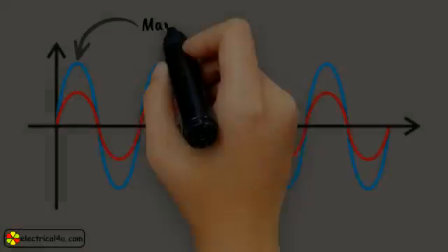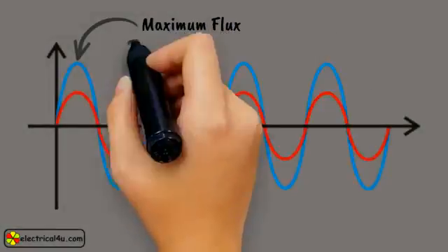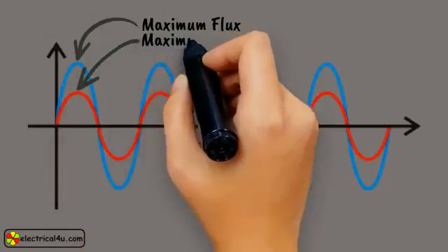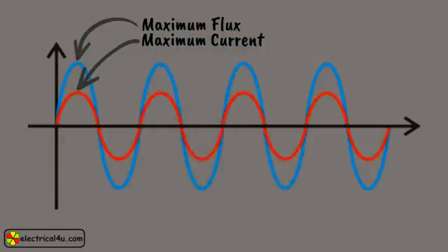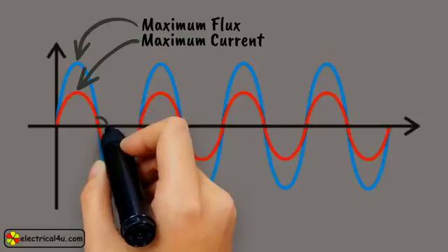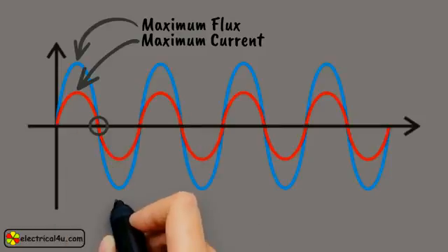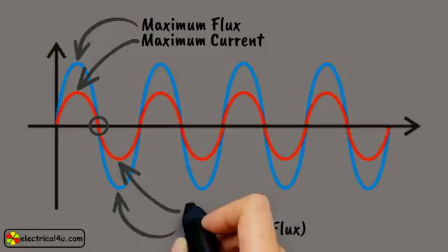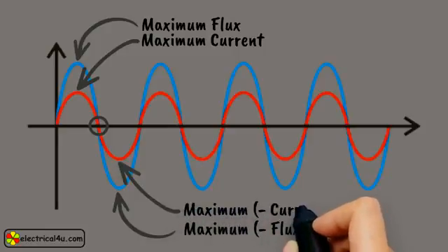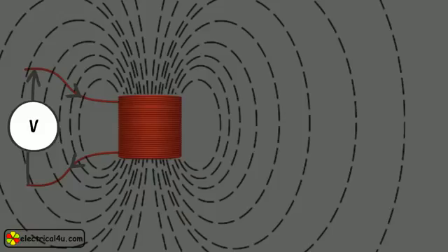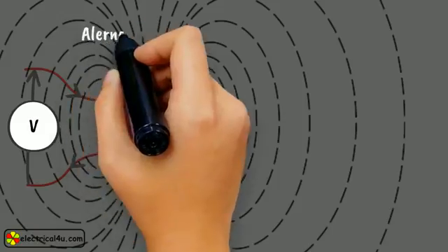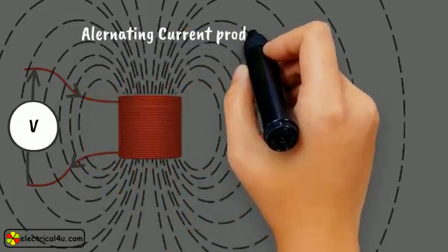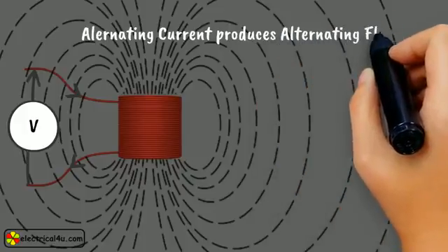This flux becomes maximum in magnitude when current reaches its maxima for 1/2 cycle of the alternating current wave. The flux becomes zero when current in the coil crosses zero axis. Again, for next half cycle, the flux becomes maximum but in opposite direction when current reaches to its reverse maxima. In this way, alternating current produces continually varying flux surrounding the winding.